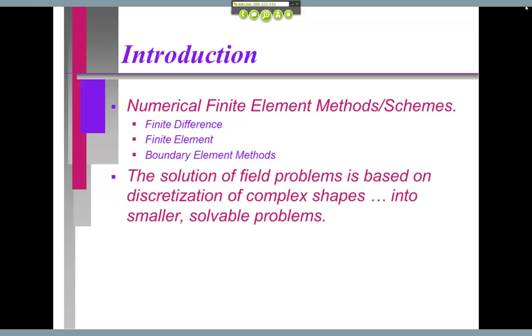The solution of field problems is based on the discretization of the complex shape into smaller solvable problems. That comment is basically to say we take a model, an object, and the first thing that we do is break it down into very simple elemental shapes that we know how to evaluate and work with.